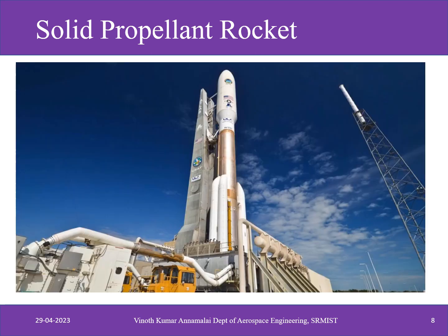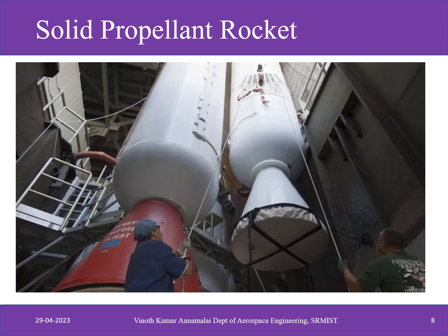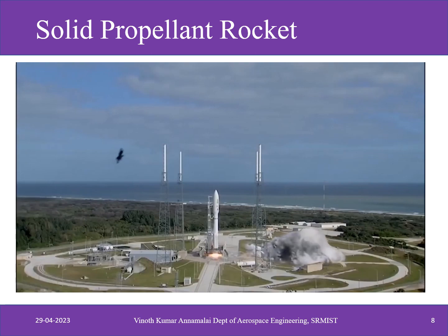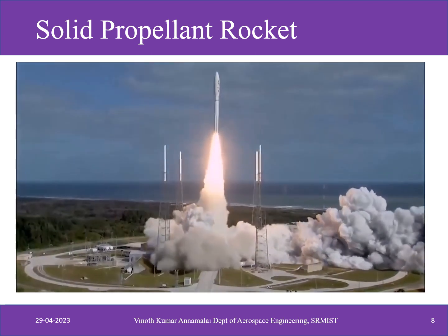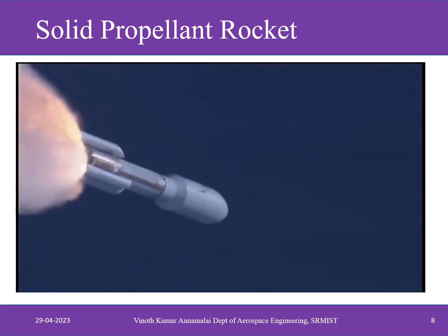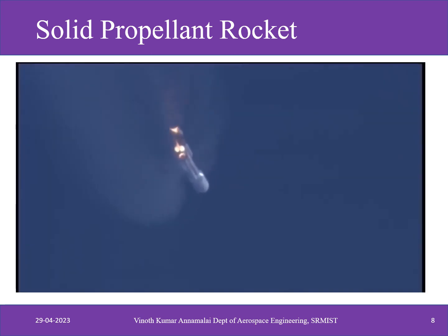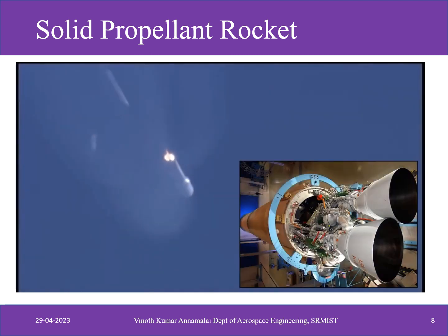The Atlas V is a rocket currently operated by United Launch Alliance, or ULA for short. This rocket uses what are called strap-on boosters to increase the delta V without adding too much cost. These are smaller solid rockets that provide some additional thrust early on during the mission. They are jettisoned after they run out of propellant, which only takes 94 seconds in case of the Atlas V. For comparison, the first stage's engine operates for 253 seconds. The Atlas V can utilize up to 5 boosters.